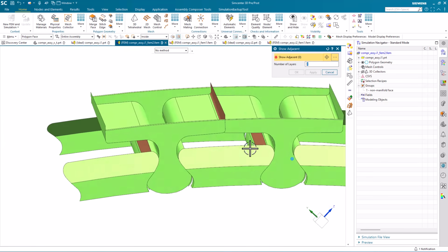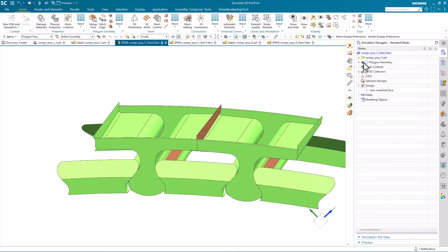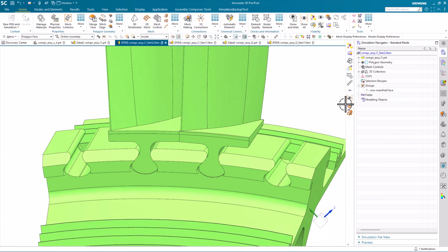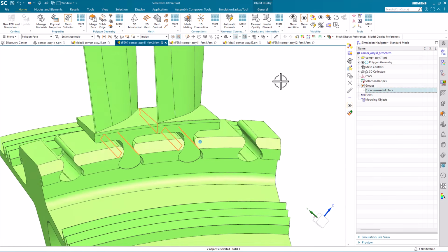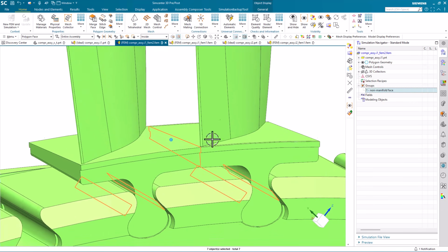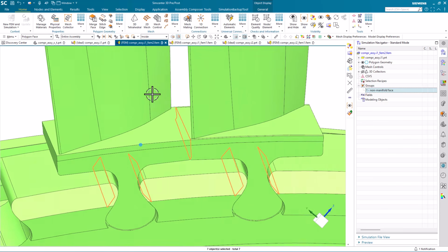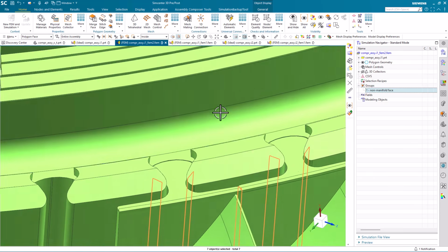But we also have an additional connection between the blades that we didn't have in our first 2 examples. So let me cancel this and go back to a full display of my polygon geometry. And if I select that group, you can see now I have a non-manifold surface going between my 2 blade solid bodies. So that's going completely through.